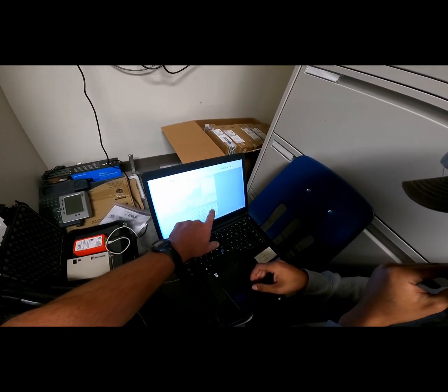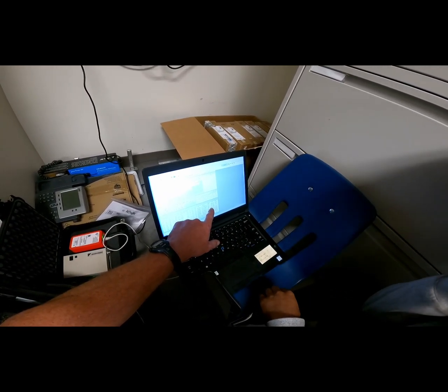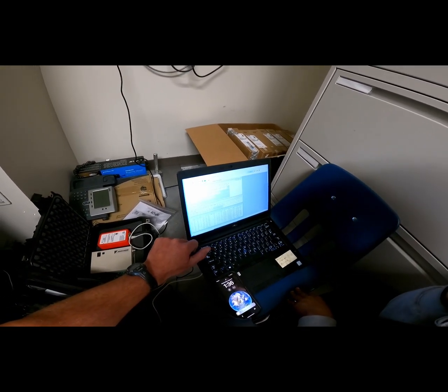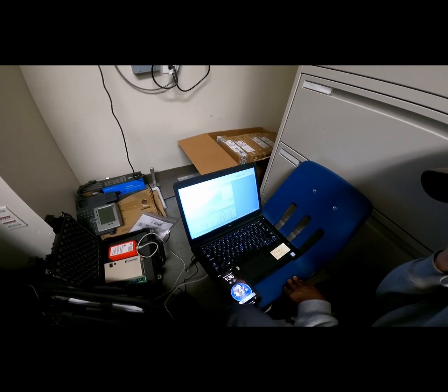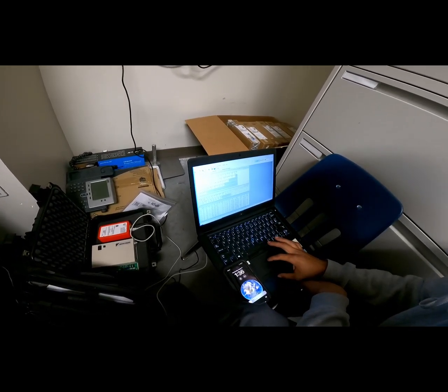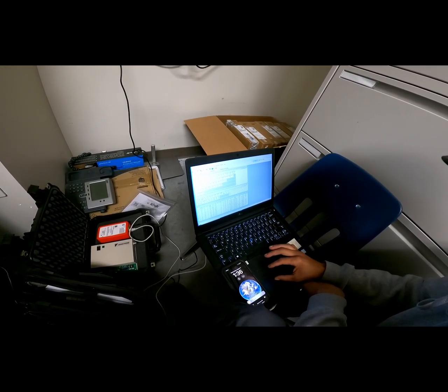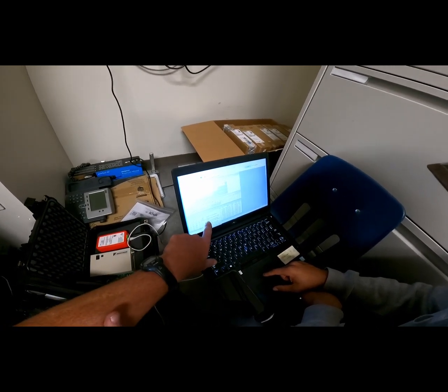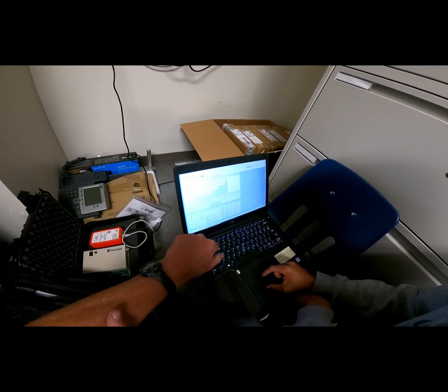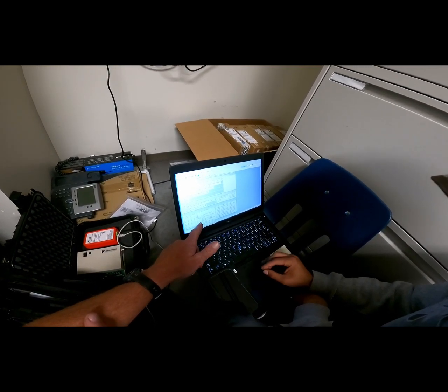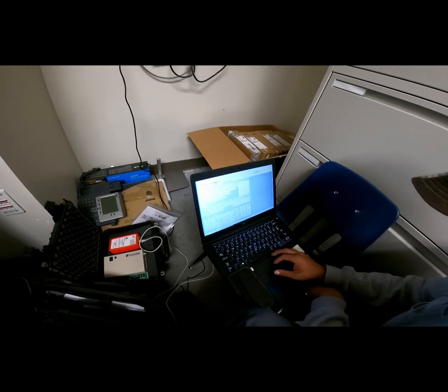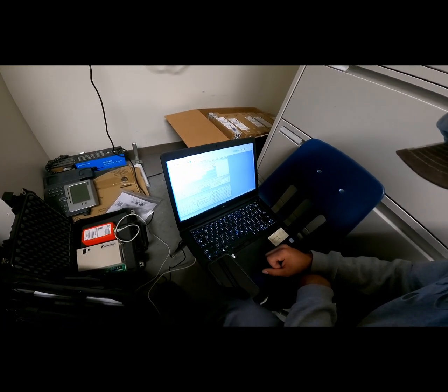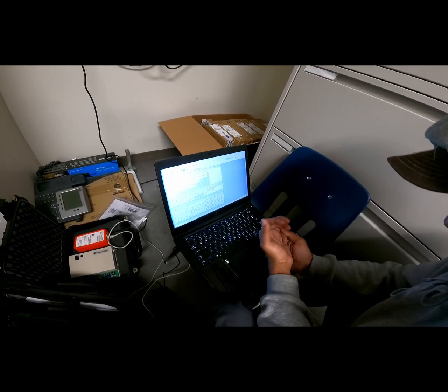Right now it shows that some of them are in heating off, some are in cooling off. It'll tell you the TH1 is, now check this out, hover your mouse over TH1 and do a left click. That's a right click, do a left click. It'll pop up, it'll tell you what the value is, thermistor, room temperature. So that's telling you the return air temperature. Click on TH2, that's telling you that it's the liquid pipe temperature.